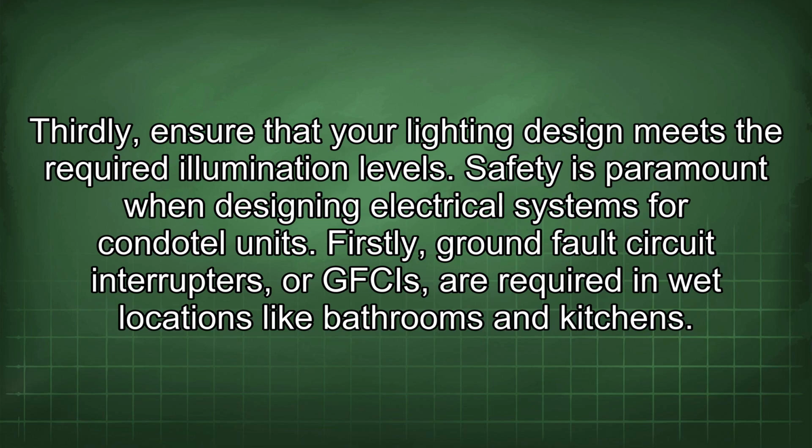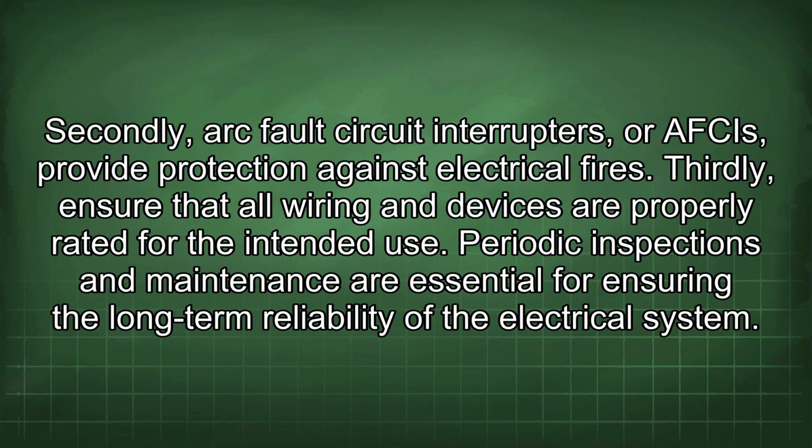Safety is paramount when designing electrical systems for Condotel units. Firstly, ground fault circuit interrupters, or GFCIs, are required in wet locations like bathrooms and kitchens. Secondly, arc fault circuit interrupters, or AFCIs, provide protection against electrical fires. Thirdly, ensure that all wiring and devices are properly rated for the intended use.